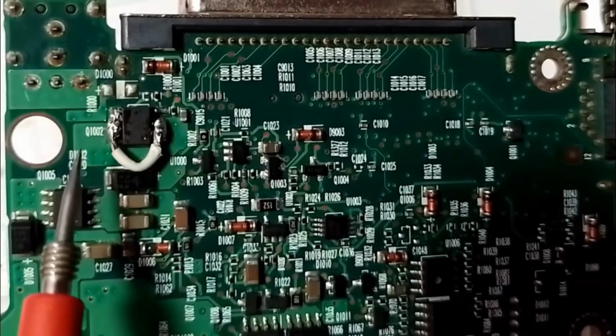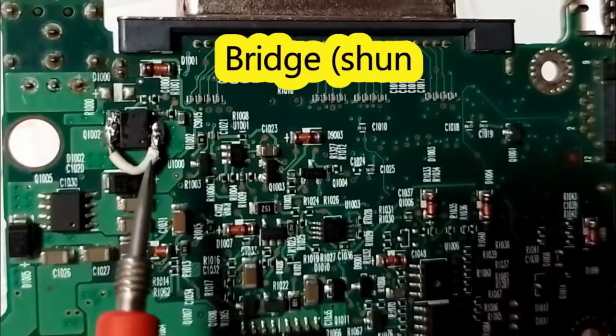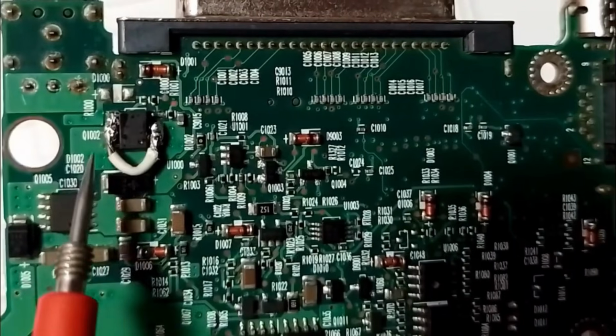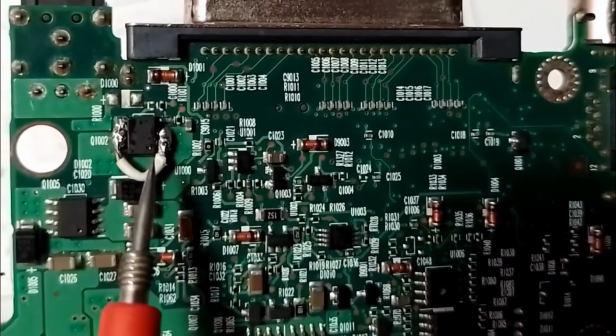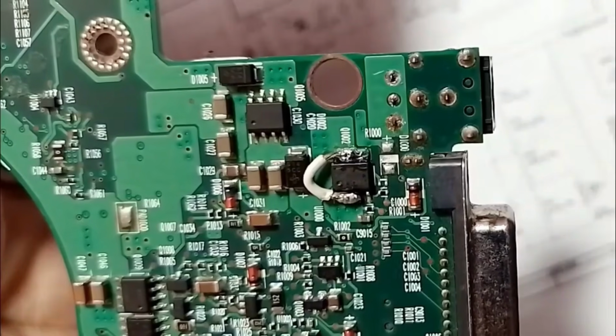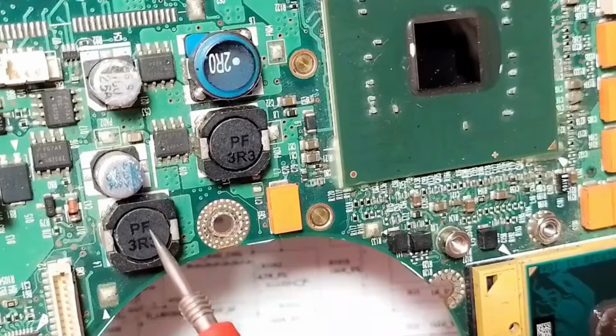I didn't find the same MOSFET with the same reference, so I just made a bridge, as you can see, using a wire between the drain and the source, just in order to troubleshoot and to find the problem. So I'm going to show you how to find the short circuit and how to solve it.